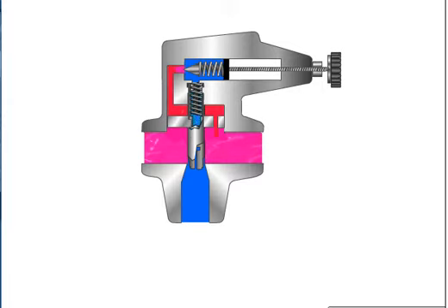When pump line pressure drops below the control knob setting, the pilot relief closes, flow through the orifice ceases, and the main spring can reseat the main poppet.